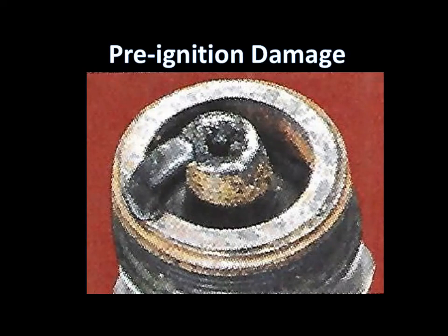Pre-ignition is the ignition of the air-fuel mixture in the combustion chamber by something other than spark at the spark plug electrodes. This is usually caused by hot carbon deposits or spark plugs with a heat range that is too hot.